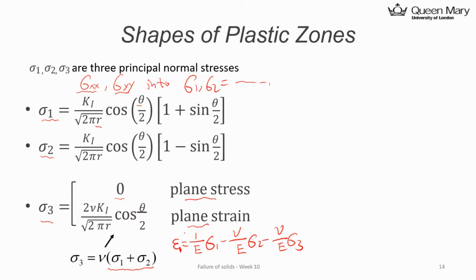By rearranging the plane strain condition, you need to look at epsilon z, which is the out of plane direction. Here, to avoid confusion, use x, y, and this is z. You can actually use 1, 2, 3, but essentially it is the same. For plane strain, this value equals 0. So you rearrange that equation and you get this, and just that term will give you sigma 3.